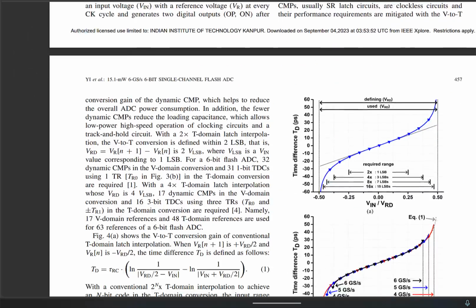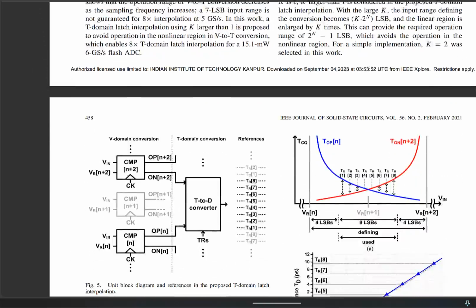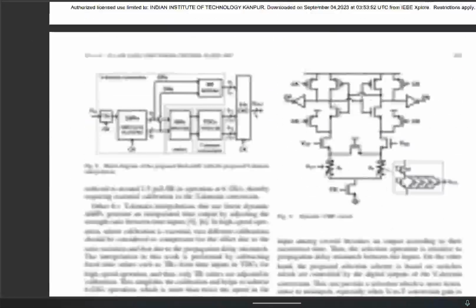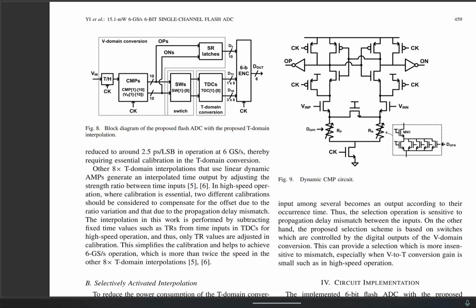And is there something interesting? Nothing major. Okay, let's look at the comparator architecture. So again, this is the voltage comparator. What is this? This is a strong arm latch. So in addition, they have all the circuits. And why are they doing this? Again, to intentionally create an imbalance, to make sure an offset is induced, and try to keep this offset almost approximately equal to your reference voltage.